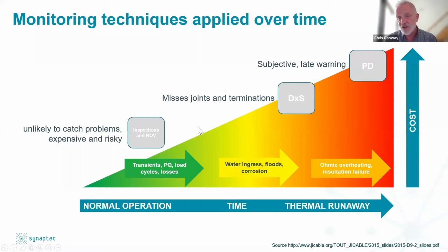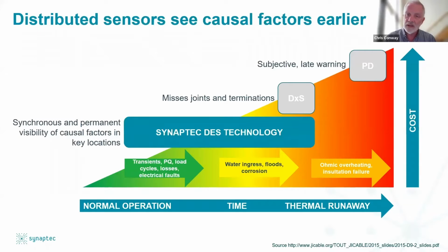And again, there's always discussion when it comes to monitoring of cables and faults. The topic of PD monitoring always comes up. That again is a technology that requires remote electronics at various locations. It's expensive in terms of real estate as well, in terms of what hardware has to be located at those places. It's quite subjective, I think, as well. So that's why we don't see that many permanent installations of PD monitoring, and their effectiveness is reduced.